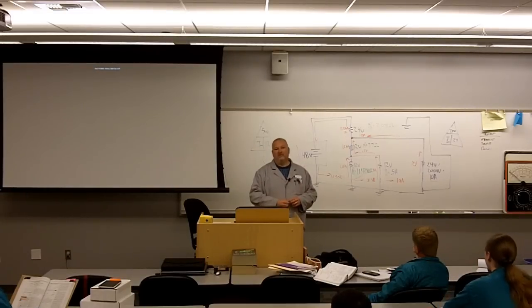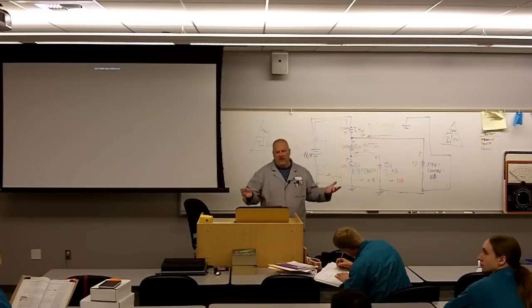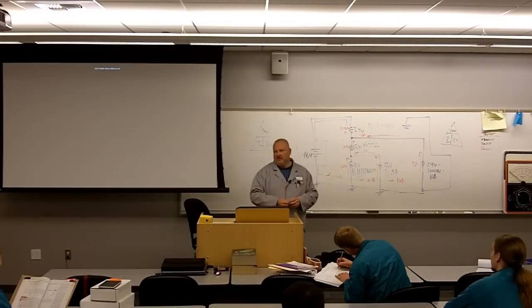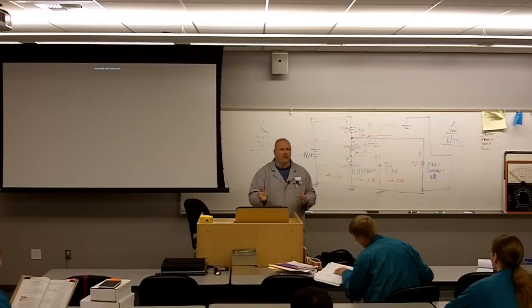So in the future, use that 1/10. If I use that 1/10, you won't get the answer that the author gets in the book. I don't know what you have to do wrong to get the number that the author gets in the book. So in the future, when you see loaded voltage dividers, use that 1/10 rule, unless you're told otherwise. You know, there might be an engineer that knows a lot more math than we know. They say, no, we want you to assume 15% or 20% or whatever. But you need some guidance.